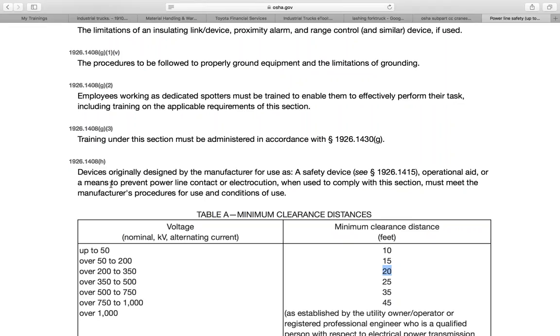How we're going to go ahead and hopefully minimize the risk of any energized hazard. What are we looking at? Non-conductive barricades, right? First of all, not using metal parade barricades, but maybe using wood or some type of plastic, like K-walls or something like that made out of plastic barricades is what I'm talking about. Also controlling the load using tag lines that are non-conductive, with either a synthetic strap or some type of rope as opposed to some type of wire rope or anything, right?